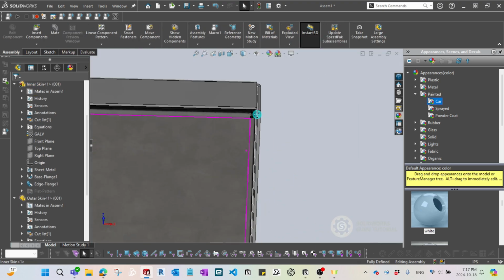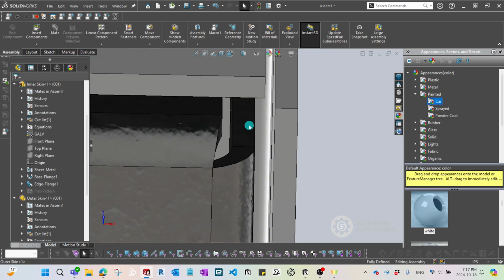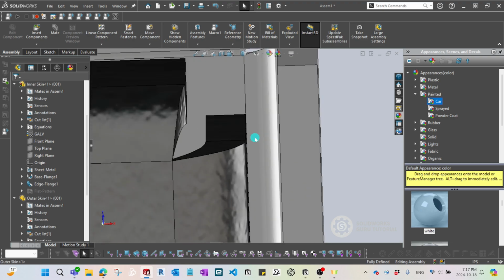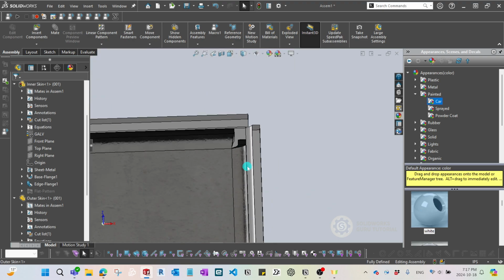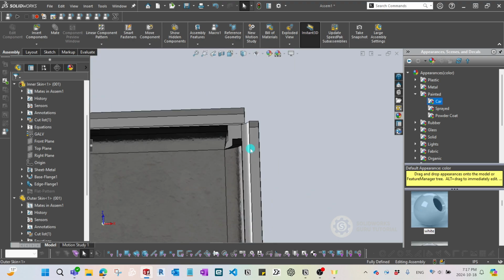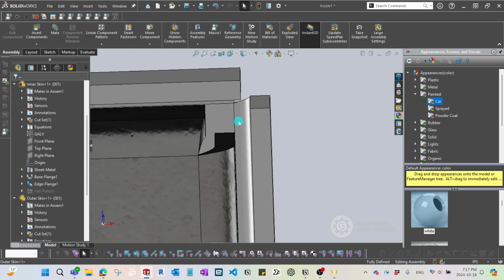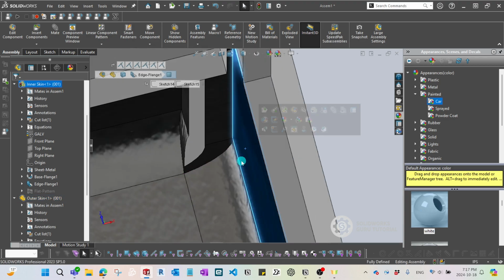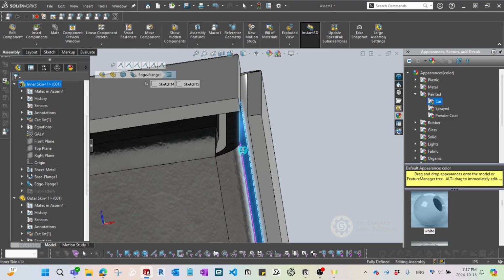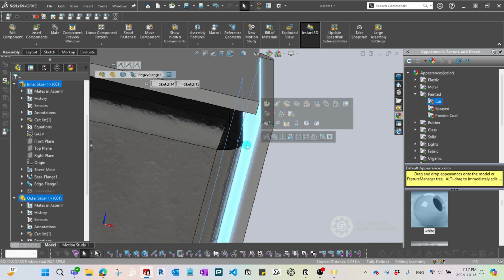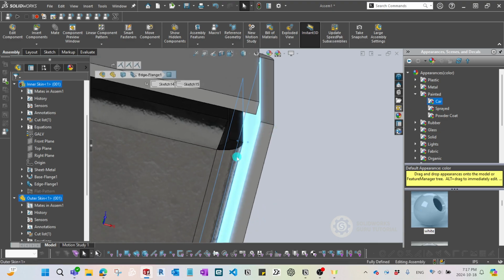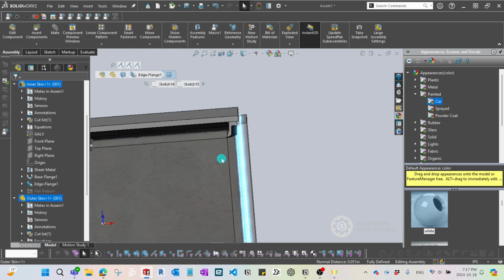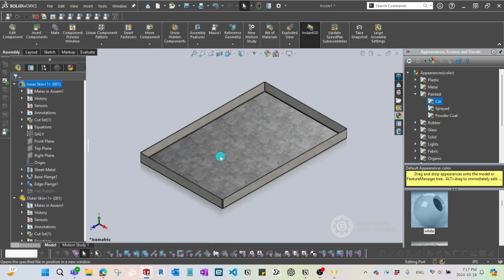Okay, so if you have a look at the bottom side, as you can see, there's a bit of gap assigned, because the thing that we only excluded is the bend radius and one thickness. But if you really want the outside of the inner skin to touch face to face, the way you can do it is basically not excluding the bend radius.